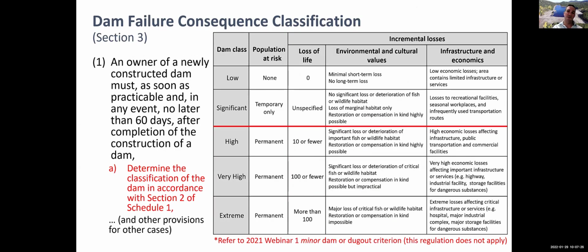So the dam safety regulation has almost a tiered level of minimum requirements. It's really based on the potential consequences of your dam failing. So the bigger your dam, and the more stuff that's downstream, or the more the loss of that water may impact people, the minimum requirements increase. So if you have a highway down below, we know a lot about highways of late. If you blow out a highway, it has huge impacts, and therefore they bump up the minimum requirements.